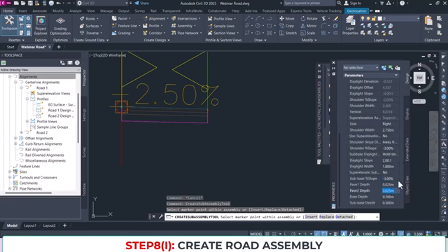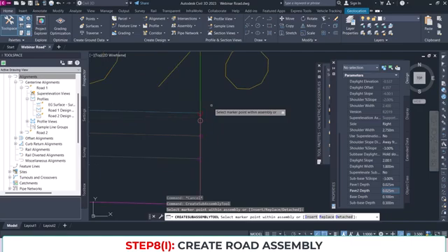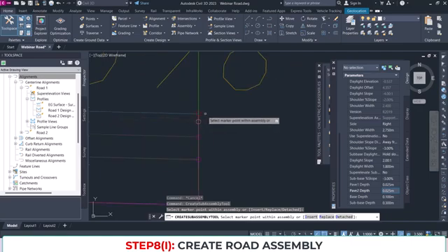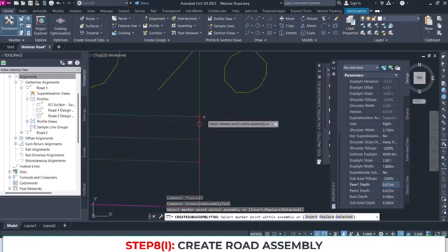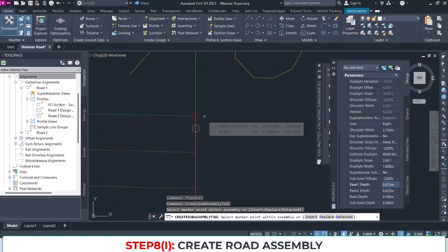What is remaining? Nothing. So let's extend our shoulder. Now, actually we don't have asphalt on the shoulder, but I'm still going to just put asphalt. I don't want to go into all those complicated things. If I don't want asphalt, I can just make it 0, because normally in Nigeria we do surface dressing on our shoulders, because it's not a travel way. It's just a service lane.